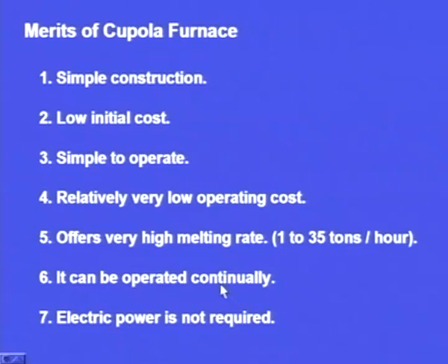Another advantage is it can be operated continually, means we charge the metal, we charge the coke, we charge the flux, and combustion takes place, and after some time we get the molten metal, again we charge the metal, the coke, the flux, we get the molten metal. So this can be continued as long as we need the molten metal.